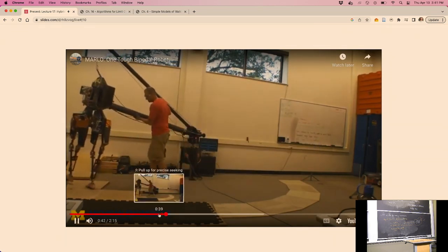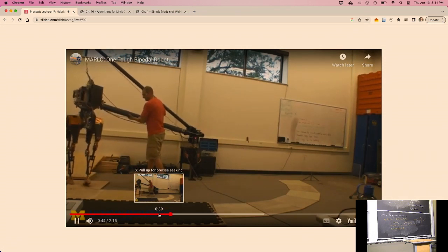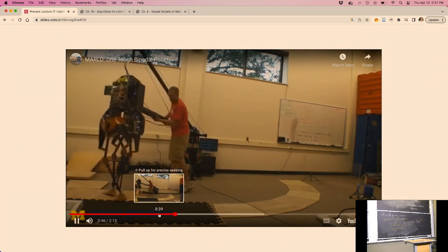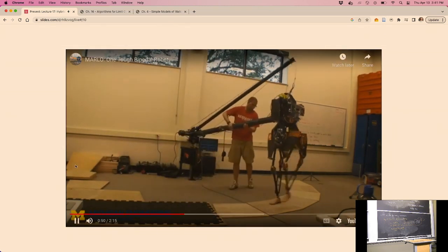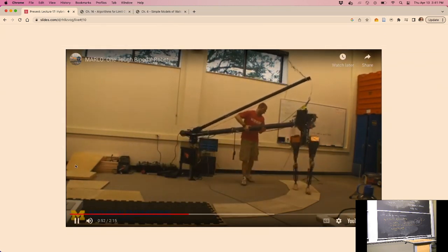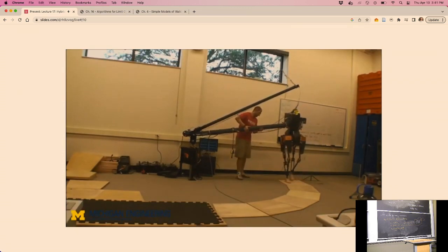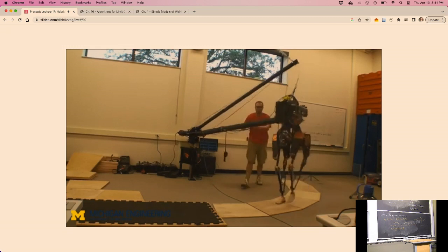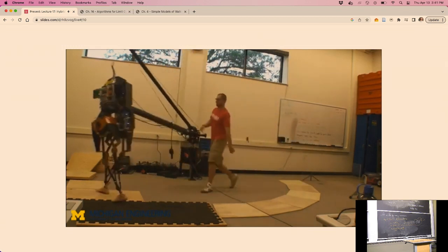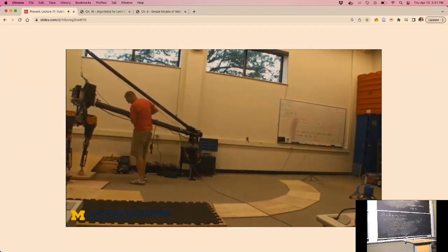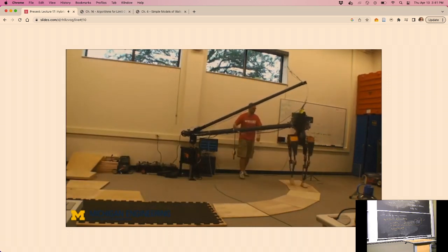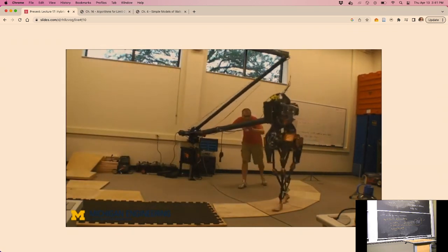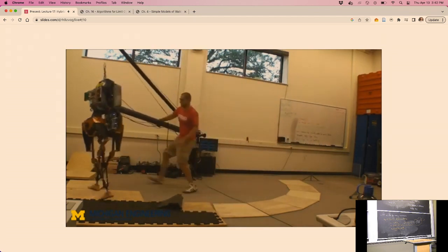Okay, so true orbital stability in this sense, their controller is actually not even doing LQR, it's just doing a simpler joint-based control using something called hybrid zero dynamics. But what it's doing is imposing orbital stability on the walking robot, okay? So much so that he can just back it up and it's like pulling it backwards around the limit cycle, okay? He's just projecting back.